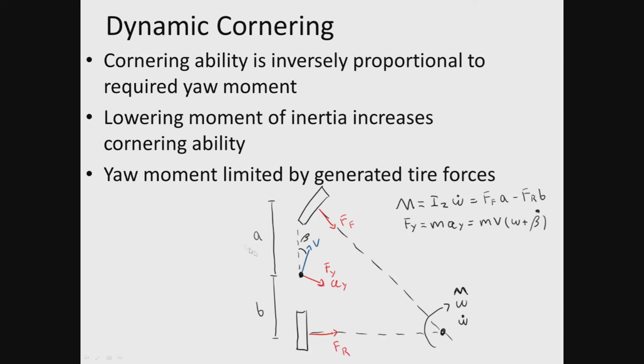And if we consider cornering as a moving force, it's not always a steady state situation. The equations shown in the last slide are a simple state. For a steady state corner, we're moving at a constant velocity around the corner, and the corner itself follows a constant radius. In realistic situations, we're going to be following a dynamic cornering state where our velocity is changing as we go through the corner. Thus, we need to be more concerned about the accelerations that we're undergoing, so the linear acceleration and how that translates into our cornering acceleration down here. And this is a much harder state to analyze, so we're not going to put all the equations down here.